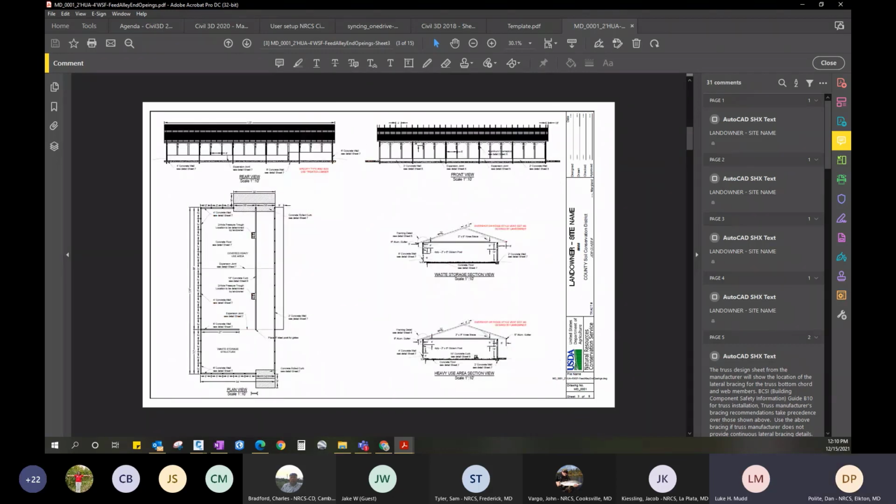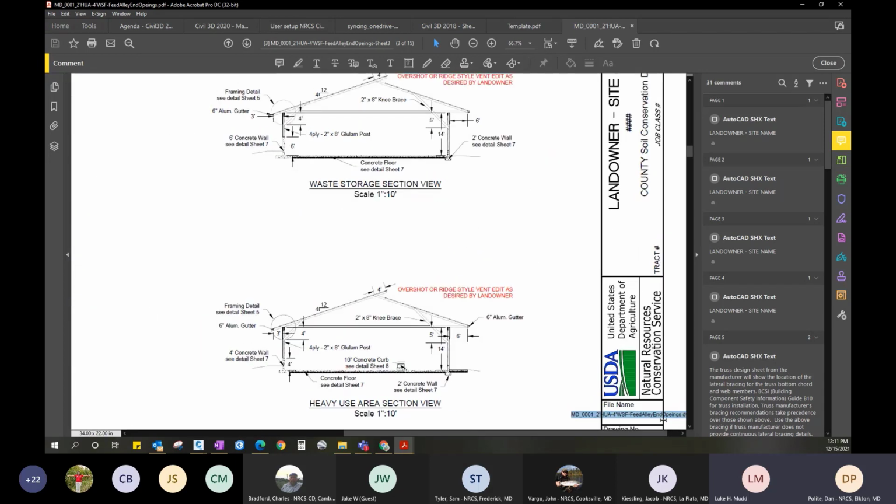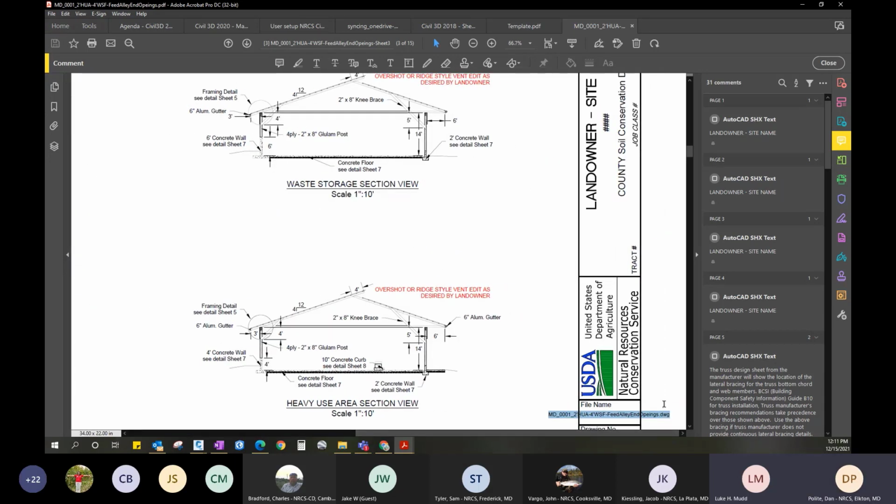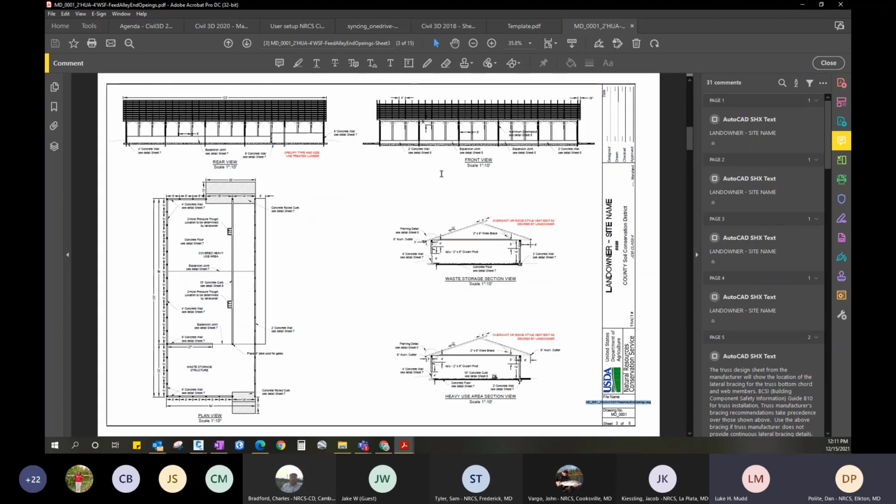If I knew this plan view was 1 inch equals 10 inches, that's not going to be to scale, because it's taken this extent and squished it down to fit this text inside of my extent. So it's shortened my entire page this much, however much this is, to fit it within the extents. If you see any PDF where that title is outside of the title block, I can almost 100% guarantee that all your scales are incorrect.